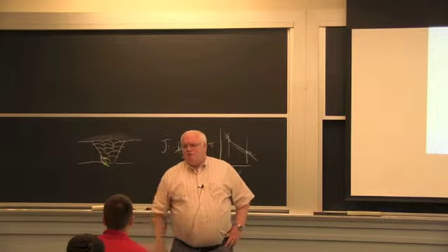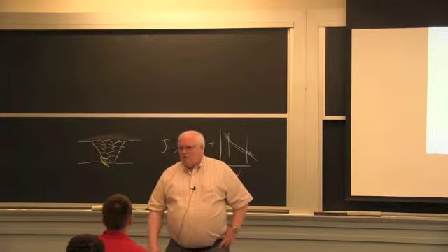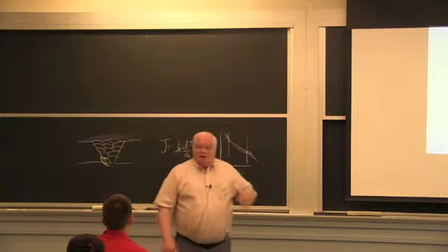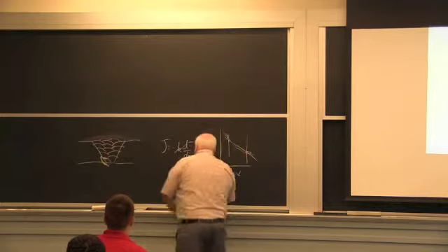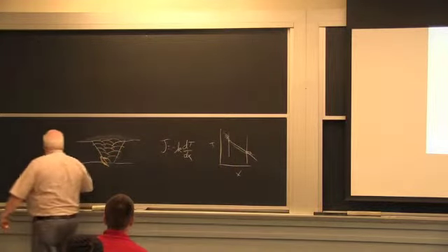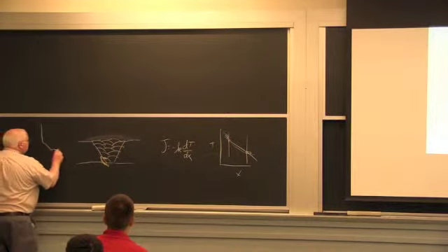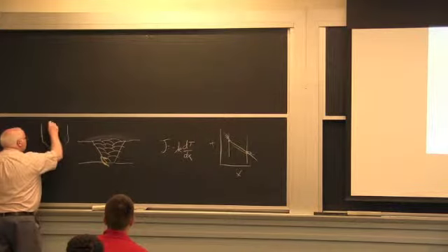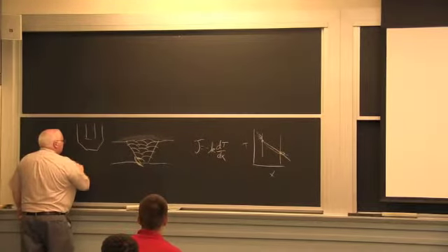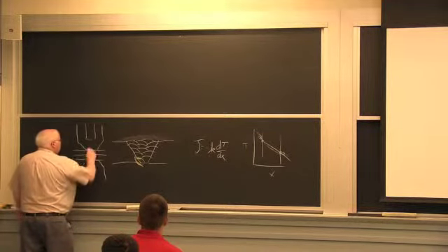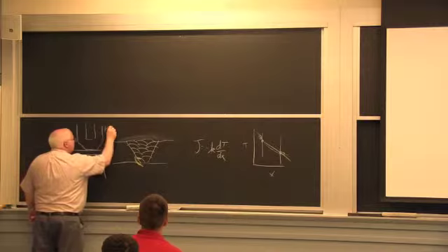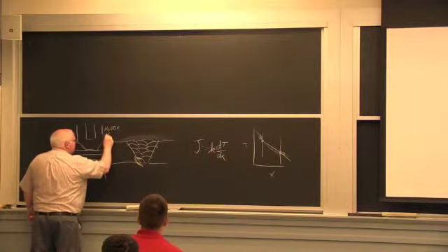You're going to see several of your homework problems, if you choose to do the problems in chapter 16, are calculating things. For one of them, you've got resistance spot welding electrodes. The resistance spot welding electrode is a copper electrode that's water cooled on the inside. You've got a piece of steel, and you've got another copper electrode here, and you might pass 10,000 amps through the copper electrodes for 1/3 of a second.